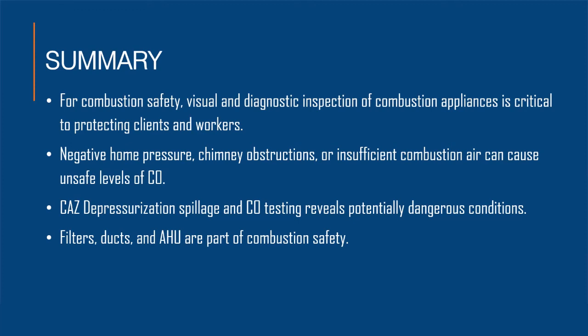And lastly, consider the ductwork, filters, and the air handler unit in your combustion safety analysis. Think of the potential of the air handler unit to create either positive or negative pressures throughout a house, as well as the potential to leak gas at the furnace or even add carbon monoxide into a living space. All of these topics are important to consider when testing for combustion safety.